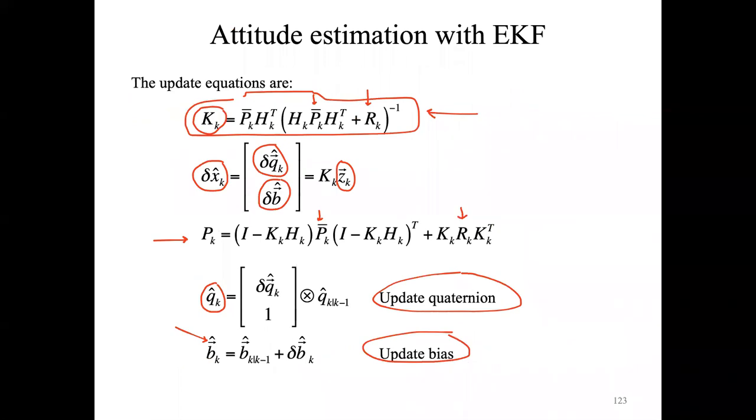So the correction of course will vary over time. You're measuring a bias at that time, but you will have a time variation of that bias that also gives information on the drift. So this implementation of the algorithm enables also to track the random walk of the gyroscope, because you are correcting the bias of the gyroscope every single instant when you have an observation.